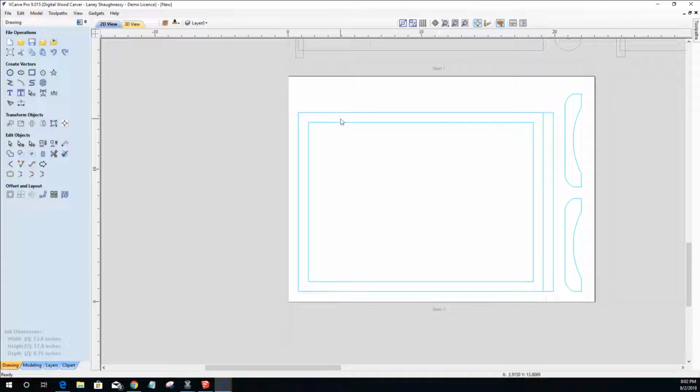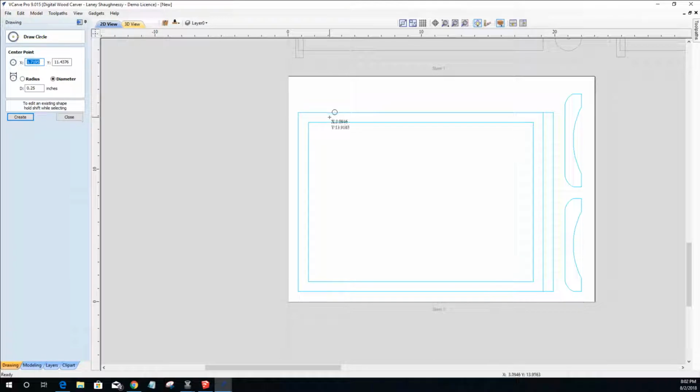Now, my router bit is going to be cutting a rabbet along this pocket, all the way around, and it's going to create a raised up island in the middle. It's going to cut this to 3/8 inch deep all the way around here, and that's the only cut on this. This area here on the right side is not touched, and the area in the middle is not touched. They're raised up.